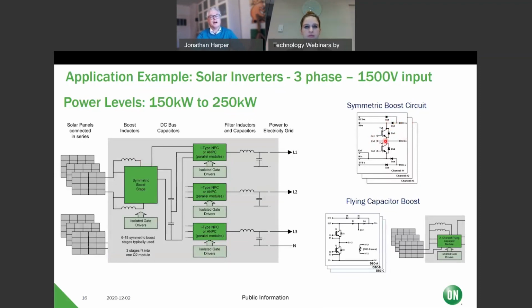So the question is, what is the benefit? We see the benefit as a simpler solution. You go back to the one inductor, you go back to a different switching frequency, and the idea is what voltage. You haven't got this stacked approach, so the idea is what voltage we need to do that. It's the trade-off with the actual rated voltage you need. 1700 volts is what's the actual breakdown voltage, right? So maybe it's 2100, 2200. It's that optimization which is important.